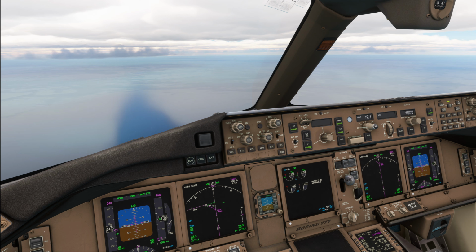During the entire approach, we're going to follow the standard decelerated approach profile, which means that we basically treat our airplane configuration, so flap extension, gear extension, just like on the standard ILS approach. So try to intercept using flaps 5 at 2500 feet above the ground, gear down, flaps 20, arm the spoilers, open the landing checklist, and when the speed allows, landing flaps, complete the landing checklist, be stabilized by 1000 feet above field elevation at the latest.